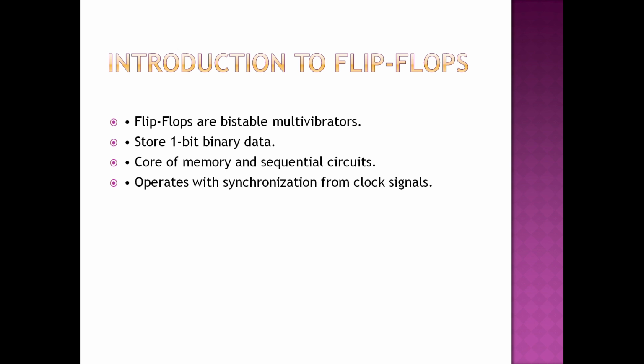So firstly, let us understand what a flip-flop is. Flip-flops are basic memory elements used in sequential logic circuits. They are bistable devices, meaning they have two stable states, 1 and 0. A flip-flop can store 1 bit of data and change state based on the input signal and clock pulse. Those devices form the core of memory registers and are used in digital electronics.